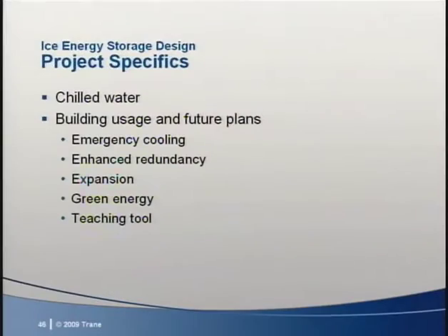There are many other building operational issues that can have an impact on the value of an ice energy storage system. For example, the fact that you can get cooling by only running the pumps can have a significant impact on backup generator sizing. More and more building owners want to strut their greenness, and schools want to use their buildings as teaching tools. Integrating the ice storage benefits into these efforts can increase the soft benefits of the system. It only makes sense to take advantage of every possible benefit.